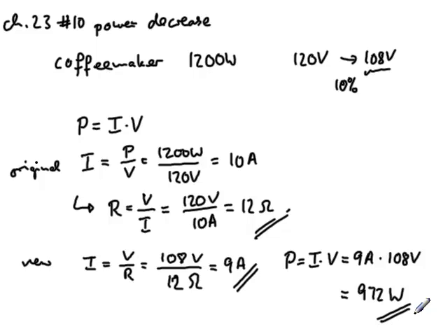Not exactly, but that's because as you subtract 10% twice, and this is what happens here, you subtract 10% here, you subtract 10% here. So as you subtract 10% twice, what you actually do is you multiply by 0.9 twice, and therefore you come up with 972 watts as the power for the coffee maker or the toaster, which means if you get less voltage from an outlet, your appliance isn't going to work as well as it should, which may be okay, just leave the toaster on for a longer time.